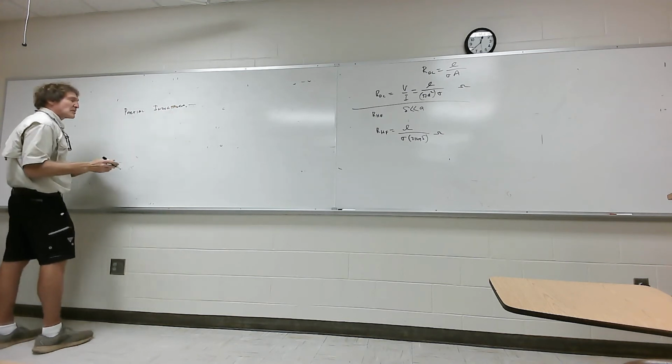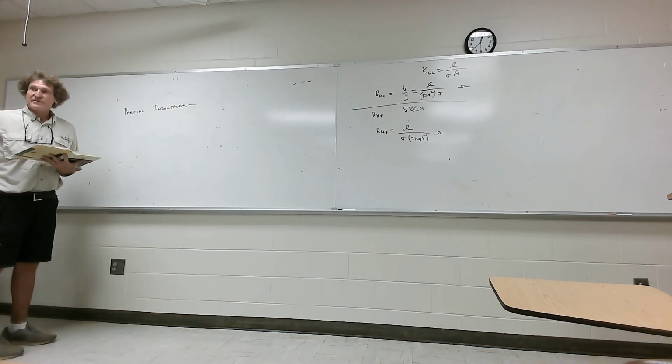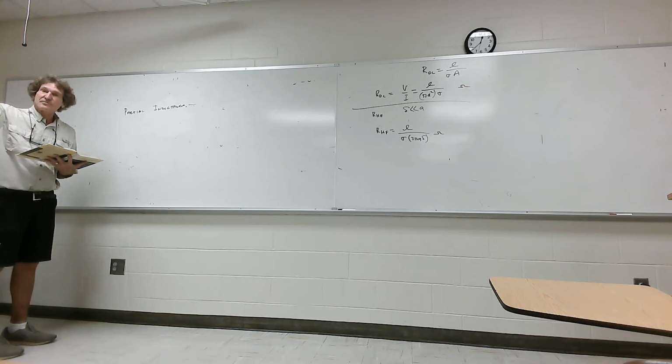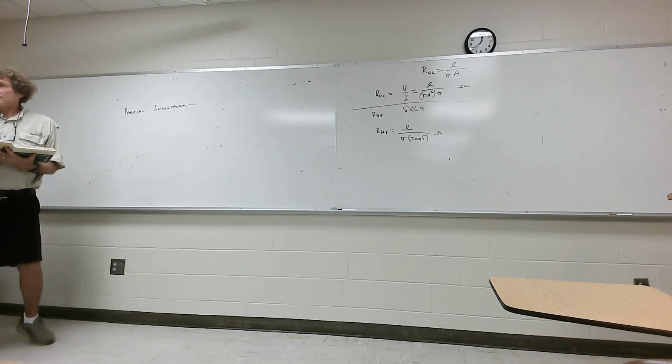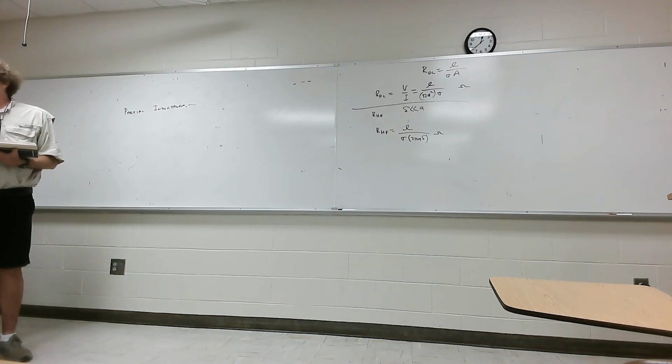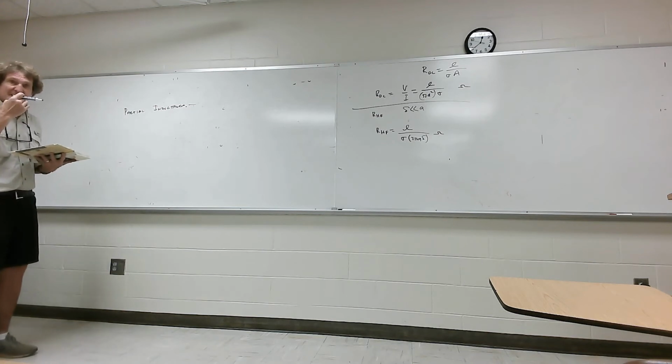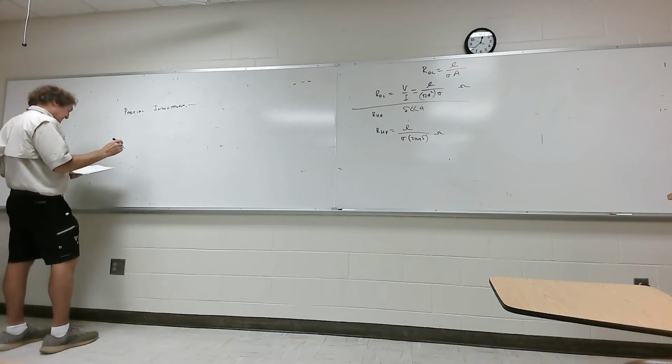So when I'm talking about partial inductance, it's an estimate of the external inductance. If we knew the exact return path for the current, we could get it. But a lot of times you don't, and that's just a fact of life. You know you got a wire going down there, and you got some current coming back here through another wire, but you really don't know the exact path of the current. You can estimate it, but that's about as good as it gets.